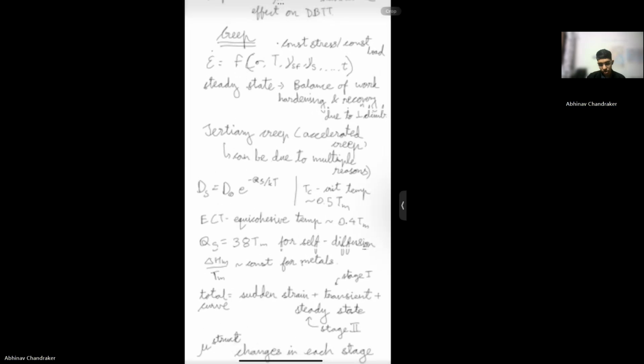Here also we have this kind of equation which resembles a constitutive equation, and we are trying to relate the properties of the material, the testing conditions, and here we have creep we are looking at. So the creep rate, the stress that was applied, which led to creeping, and the time for which the creeping or deformation happened.